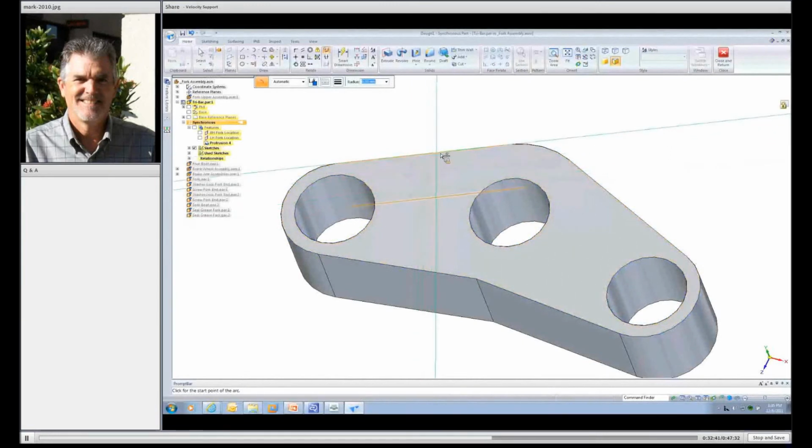That makes it about 80 millimeters tall. So what I'm going to do at this point is create a cut. It's going to be awful heavy if I don't remove some of that material. So I'm just going to use a simple line command. I'm going to lock to my bottom face and draw a line, making sure I'm point on, and then I'm going to mirror this to the opposite side.